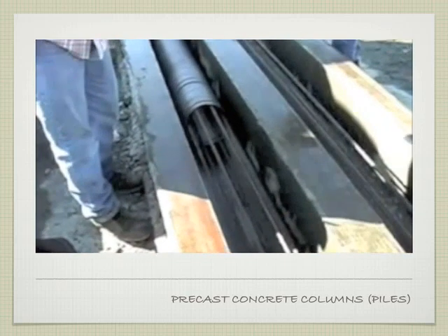All those wraps, those ties, they're using what would be like a giant slinky. They string that in, and then they pull this down from one end to the other, and they just tie it off in a few places, and that provides that other layer of reinforcing.